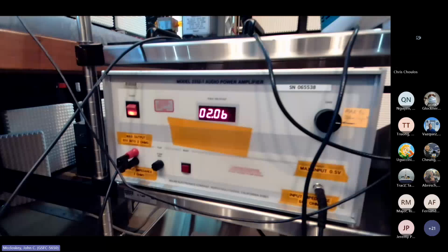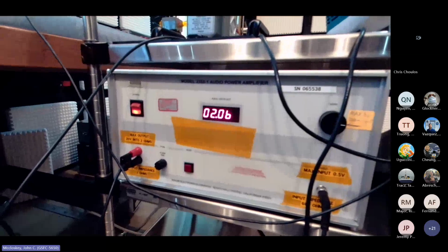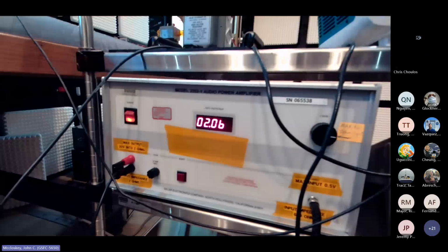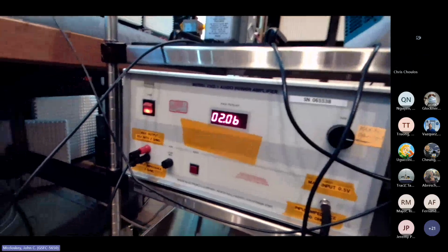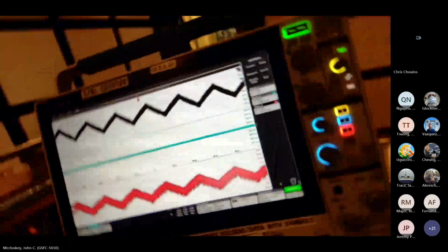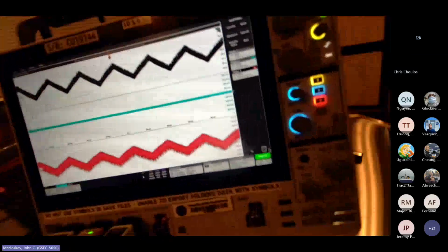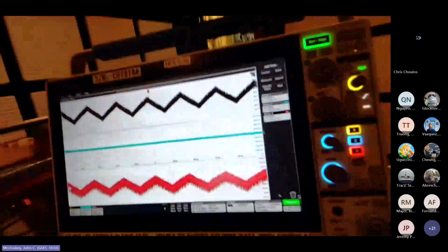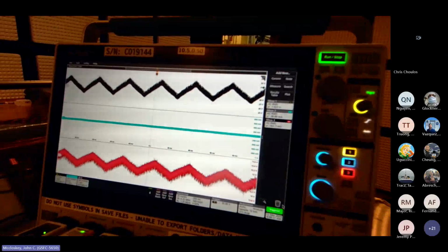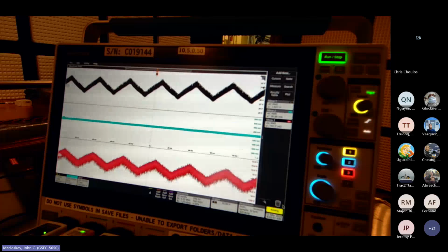At 150 kilohertz, you're going to have inductance and other things that make that impedance something different from what you think it is. But anyway, when you're doing CS101, the pre-calibration step and/or the current monitoring is an extremely important part of it. Don't forget that.